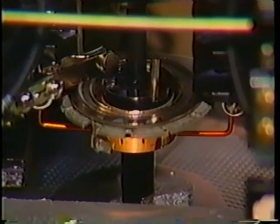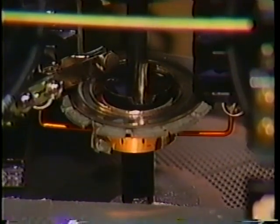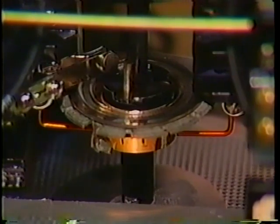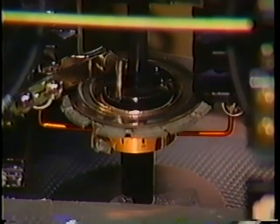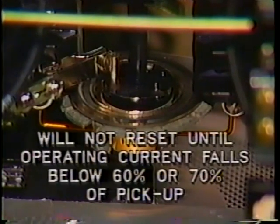Once the disk is rotating under fault conditions, inertia will cause the disk to continue slight movement, even if the current falls below pickup value. This over-travel could cause inadvertent tripping. Moreover, the disk will not reset immediately. In some relays, not until the operating current falls below about 60 or 70% of pickup.